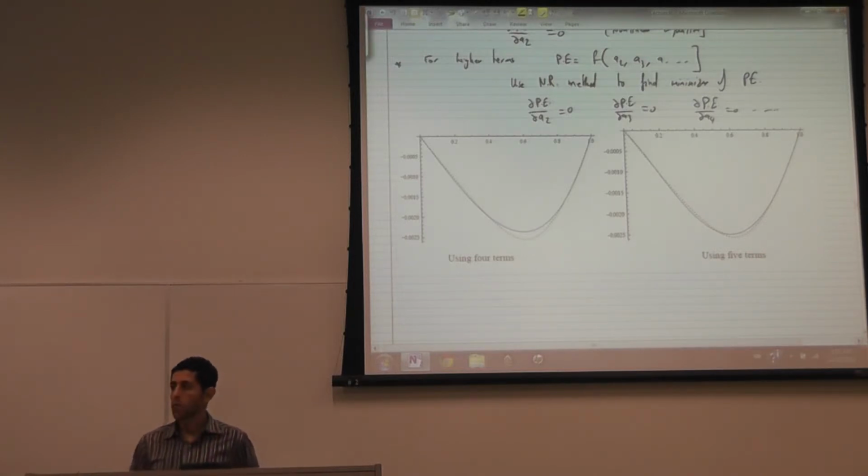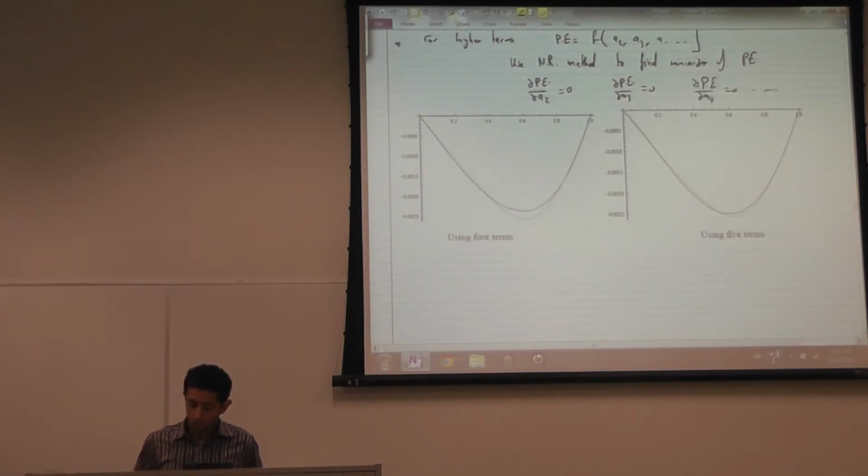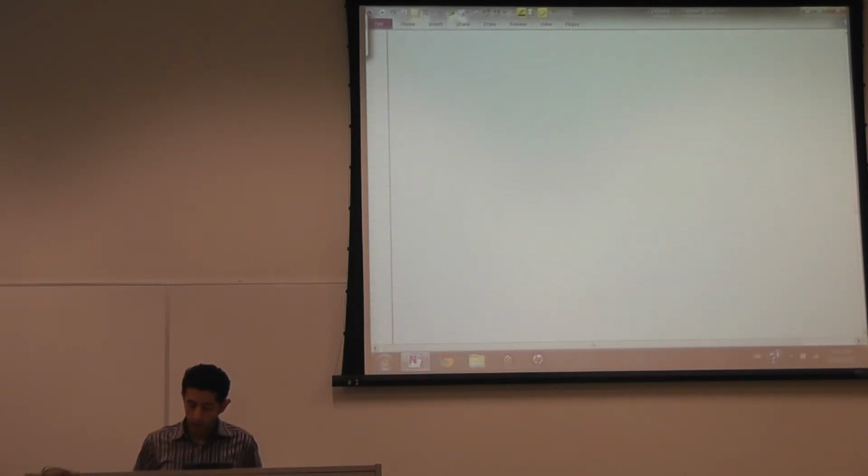So this is an example where the relationship between the stress and the strain is nonlinear, so I have to utilize the Newton-Raphson method to find a solution to the equation of equilibrium, or to minimize the potential energy. Another example is if I have material nonlinearity.